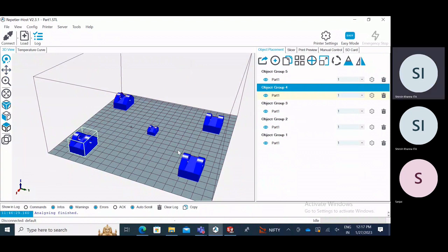And last, if you want to, no, it is not like this. I want to place it as a mirror. So one thing we can do, we can rotate it. If you want a mirror, we can rotate it by this Z-axis 180 degrees. We get the mirror object. But if you want a direct mirror option, here we have the last option, mirror. This is mirror object. You can use the M command.